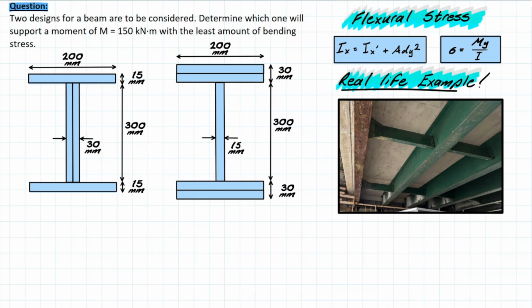So recently I was looking at this bridge that has girders spanning from one end to the other. And you're going to notice that there's two different looking girders in this problem. We have one on the left that has some levels of corrosion buildup, and one on the right that looks relatively good condition. And I want to highlight this one on the left here, which is going through that rusting. The chemical process for rust eats away at the original steel and builds up this flaky debris that is no longer contributing to the flexural strength of the member.